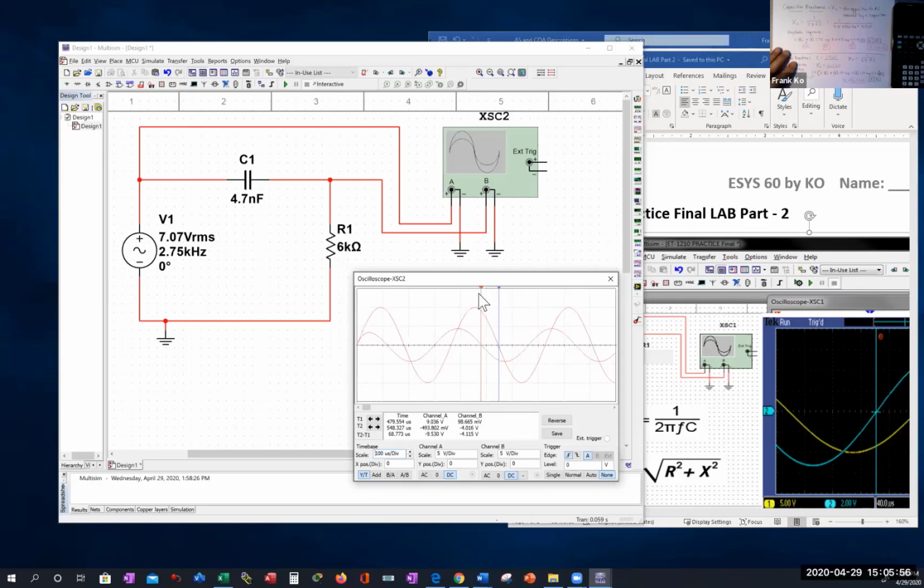So cursors, where do we get them from? We get them from the far margin of our oscilloscope display. I'll move them both back over here. So this is your waveform after you've gotten it stabilized, after you've gotten it filling the screen, after you've gotten it widened or narrowed. This is too wide. This is too narrow. This is good right here.